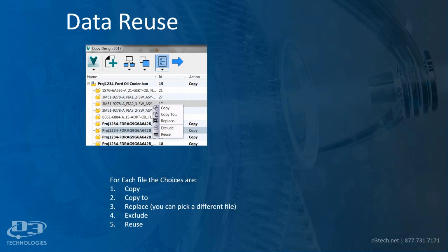Is there any other questions here? Yes, so the other question is, can drawing review and approval comments be captured inside of Vault? And yes, so when you make a transition, there will be a comment field where you can make a comment on that file.